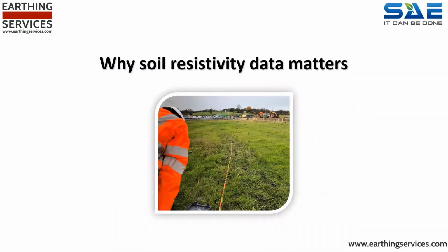Historically, installation companies may have offered to drive a single earth rod and take a range of readings from it at various depths as it is driven into the ground. But this is no comparison to the professional approach. The only thorough, scientific and logical method of determining an electrical earthing system is to undertake a complete soil resistivity survey to an approved methodology.